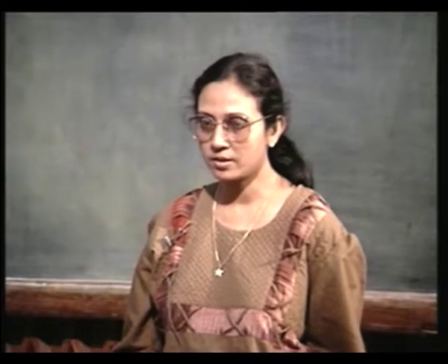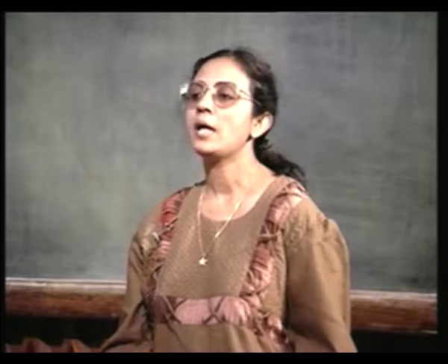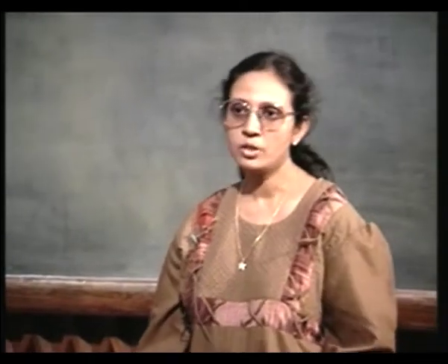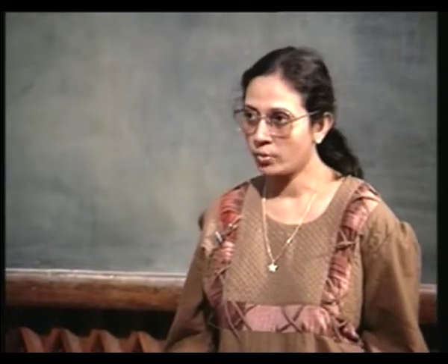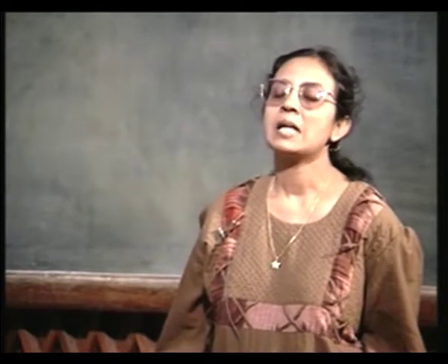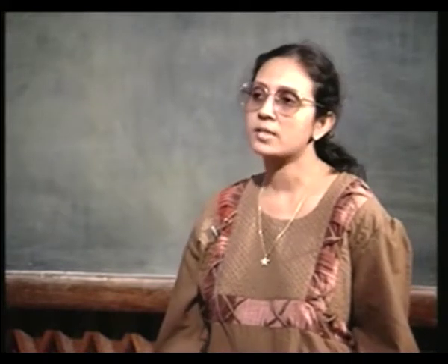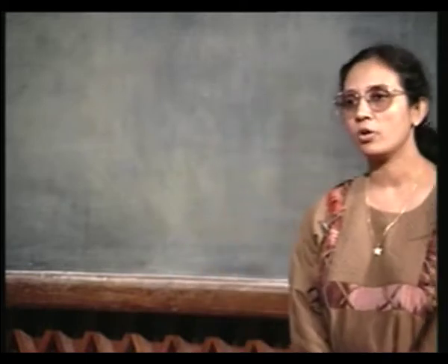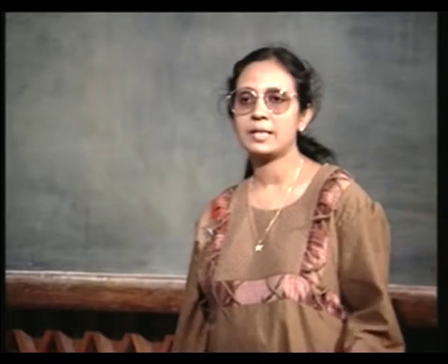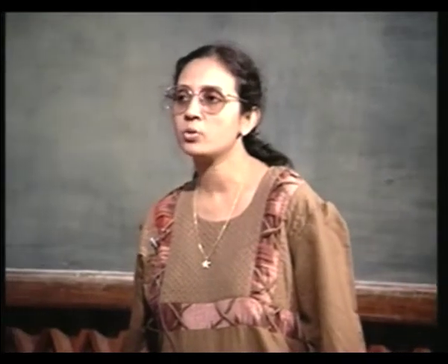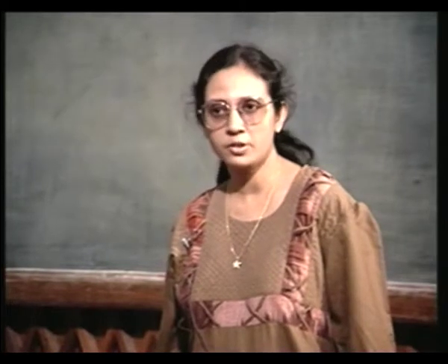So, this NPN transistor is operating in the inverted mode, and you have already seen that we can either add an N plus collar to this I2L circuit if we want to facilitate hole injection in the direction of the NPN transistor, or we can replace this N plus collar with an oxide isolation also. The oxide isolation will have the advantage of space saving, but at the same time we have to provide multiple base contacts if we want to avoid the problem of unequal drives.